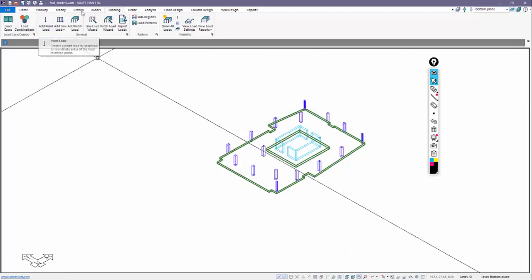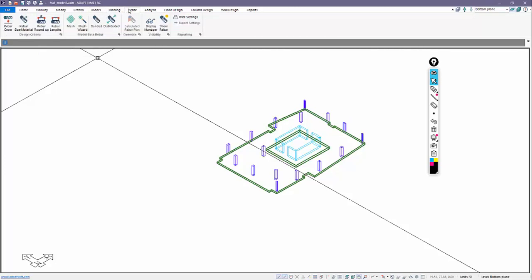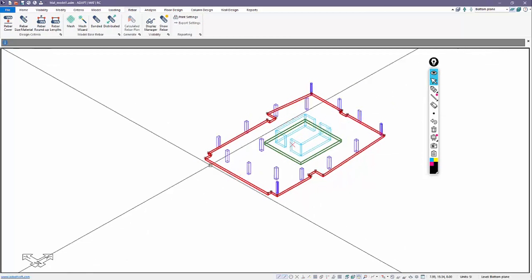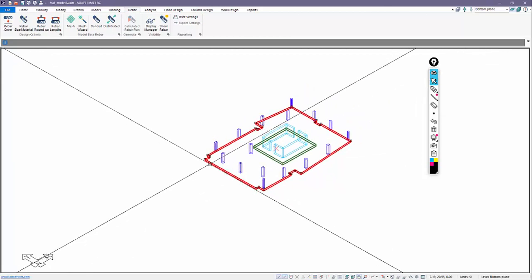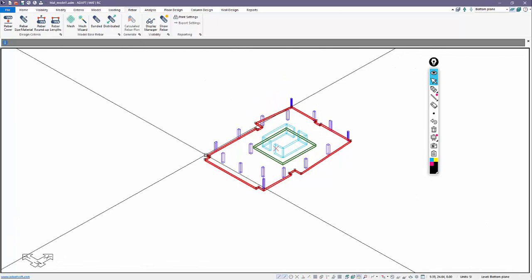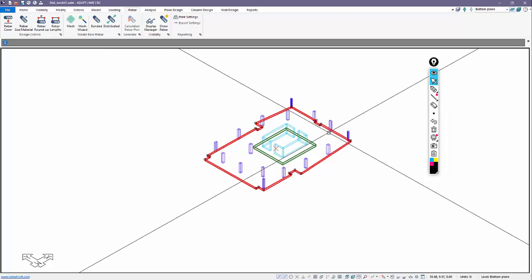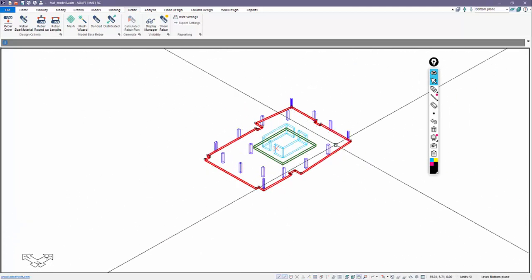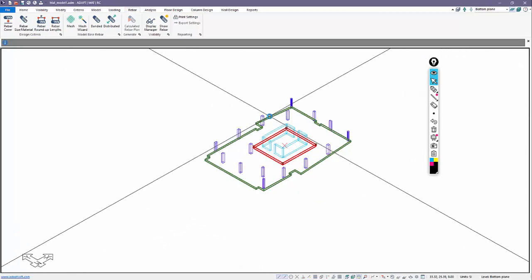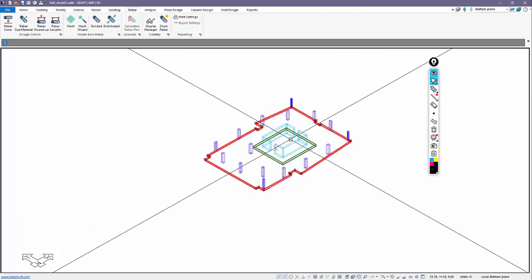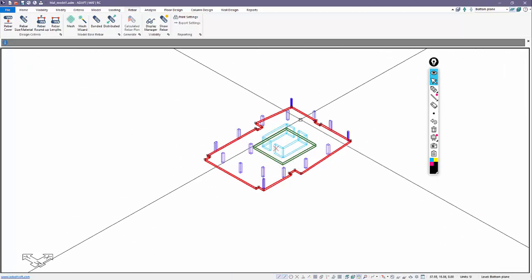Now, if we go to reinforcement, I want to select the slab, and I'm going to add a top mat of steel. And it's important to understand how this has to be done when you have nested slabs like we've input them. The program will use the slab that was entered first in sequence really as the reference for how the bars are positioned. In other words, the cover. So if I select this over this slab here, the thicker slab is actually at the same plane at the top as the main slab. So it's okay to select the main slab and then assign the reinforcement.